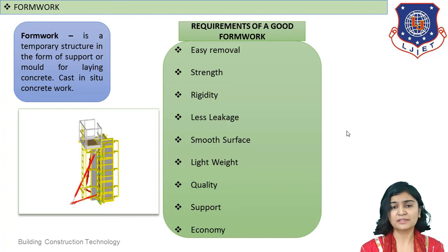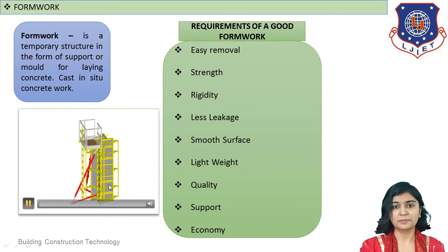These vertical supports shall be in the form of timber or steel props. Support is important because if you do not provide it, the formwork may deflect or displace from its position because of the poured concrete and cause failure as well. So support is important when you talk about formwork construction. And last is economy, which I already discussed.